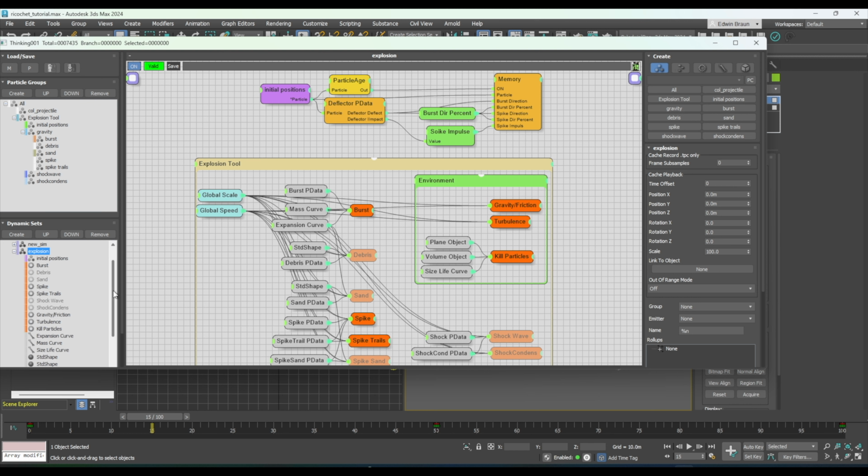And when I say at the top, as usual in Thinking Particles, hierarchy is important, it's crucial, and it's also the most powerful tool you have at hand. Because the hierarchy allows you to play God and decide which operator is evaluated first, second, third, and so on.